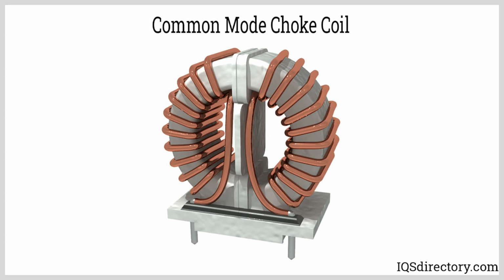Choke fully open. When the engine reaches normal operating temperature, the choke is fully open, allowing an optimal air-fuel mixture for efficient combustion. Application of the engine choke. Carbureted engines. In older cars and motorcycles with carburetors, the choke is essential for starting the engine in cold weather.